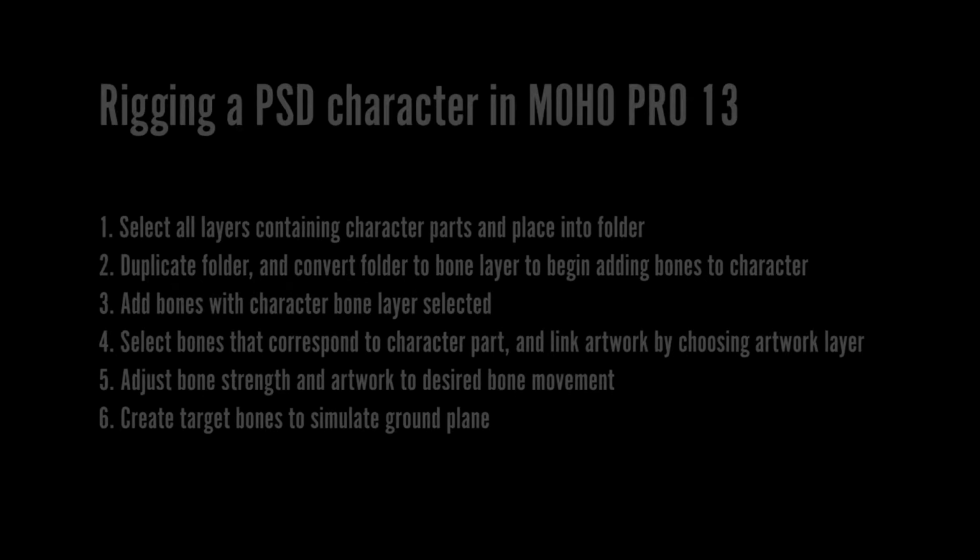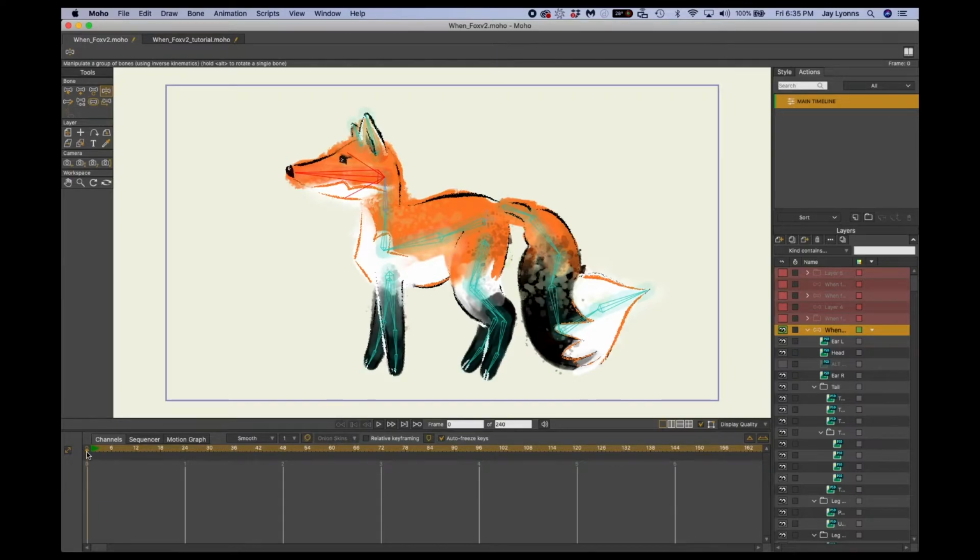One important thing to keep in mind when we're creating our character is that all of our designing is done in frame 0 of our timeline. Anything past frame 0 is used for animating. Anytime that we're designing or editing a character, we need to be in frame 0.